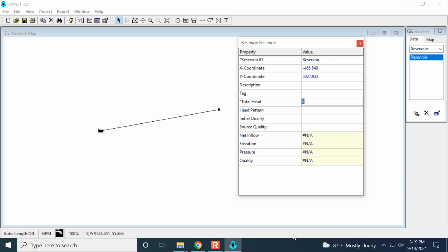But then instead of allowing it to spray all over the place, if you confined it with a piezometer, the water level would rise to a certain elevation that is reflective of what the pressure in the pipe is. And so I talked about the pressure head. And that is how high did the water level rise in the piezometer as a result of the pressure in the pipe. So that's another place you've seen this word head before, was when we were talking about flow-through pipes.